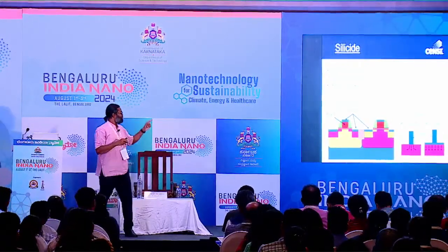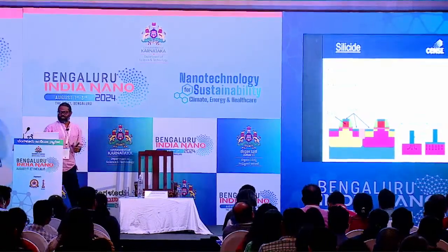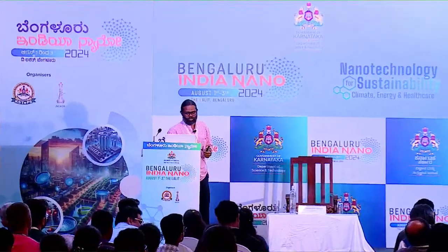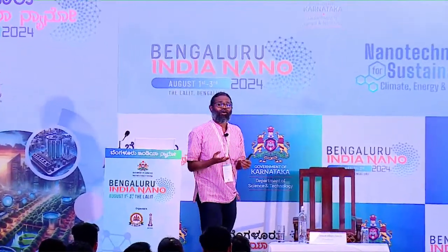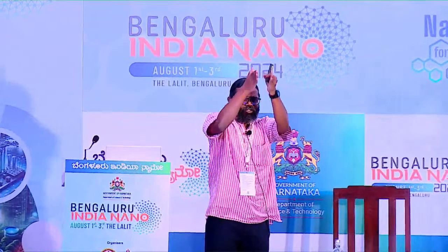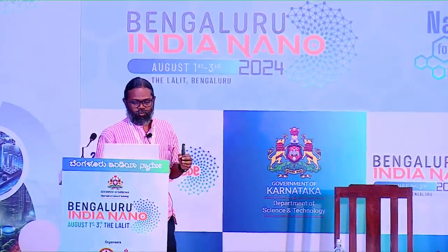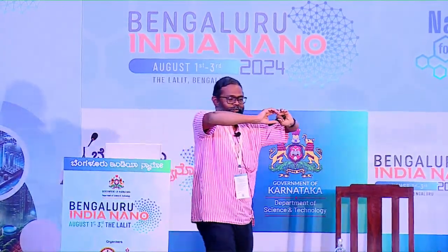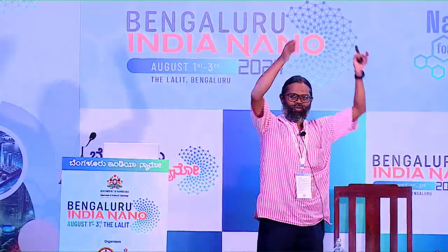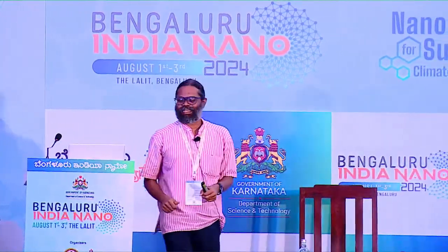Something else happens, that's what is shown here, which is called parasitics or current crowding. All the current is going through that small contact. You don't want that, because that becomes a weak point for failure. So what you want is a conducting layer that is flat, where your contacts can come and end, right? That is called a silicide.